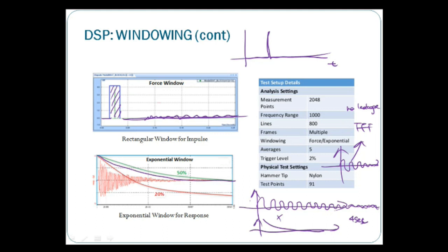Cannot. Hanning, because the function is some sort of like this, right? It starts at 0, so you will basically force this part. You see, in a transient signal the important information is all here. If you put a Hanning window like this, the end will be 0, but the front part will also disappear. So you lose the important information. Yeah, correct.